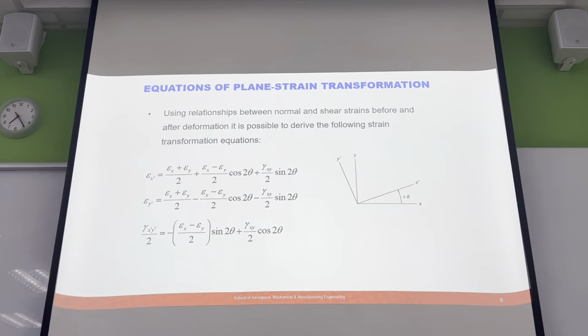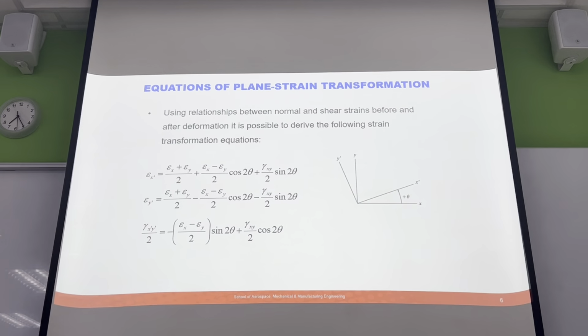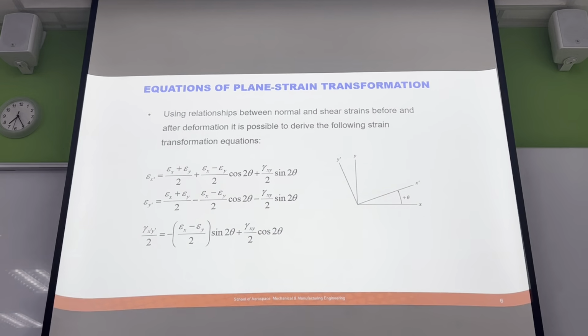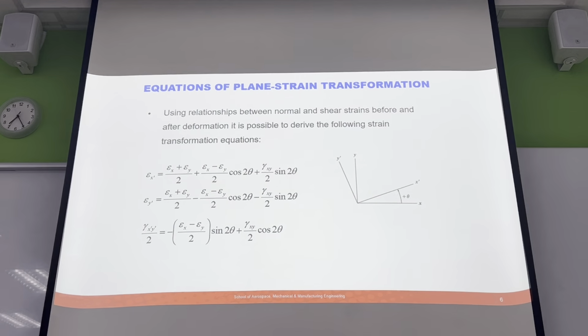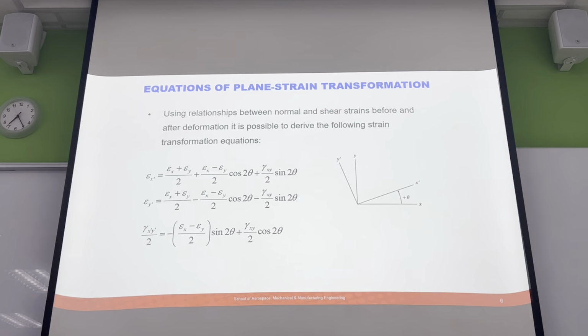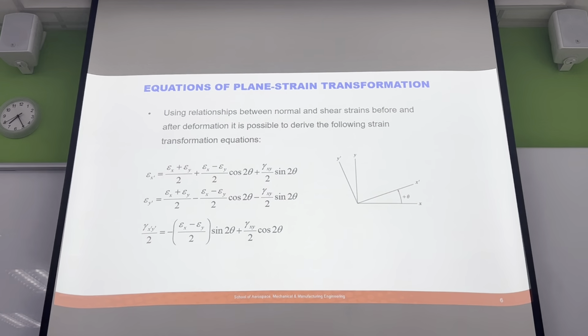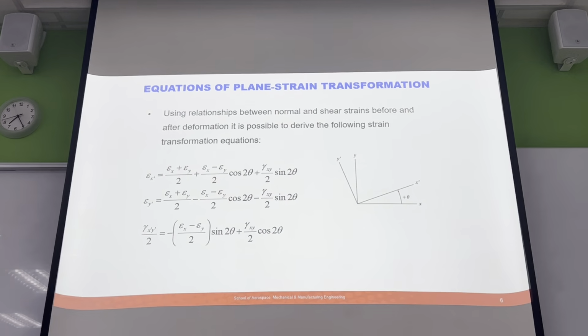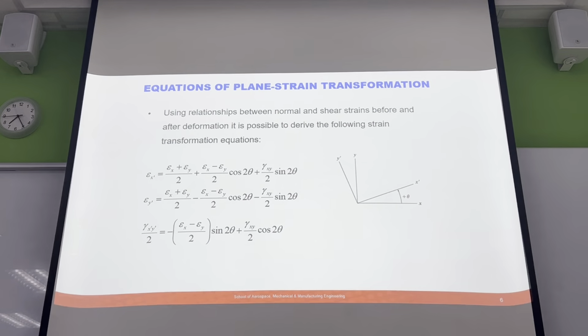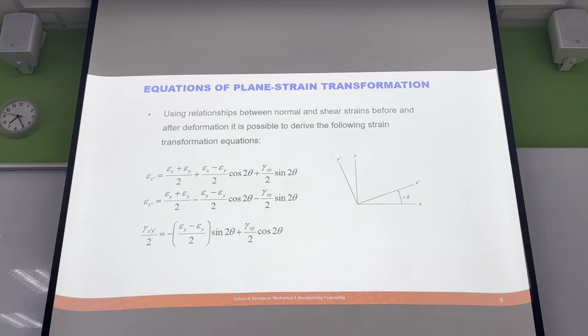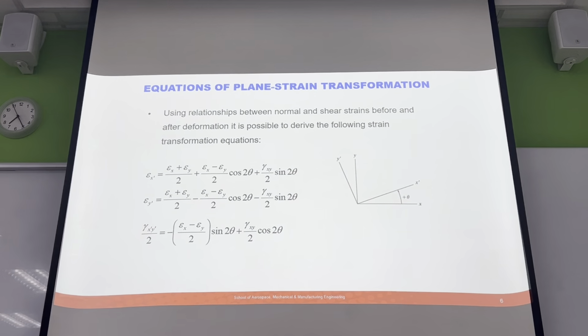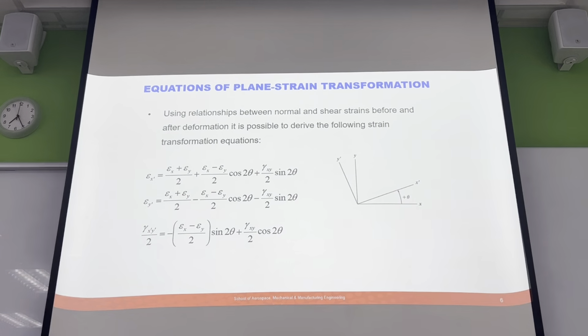Now, you might think, oh, these are really not as useful. I will tell you, if you're doing experimental work, or if you're doing in situ engineering, like maintenance things, you're much more likely to use these equations than you are to use the stress equations. That's because you can actually measure strain. You can't measure stress. There's no stressometer you can put on something. But you can get strain gauges.